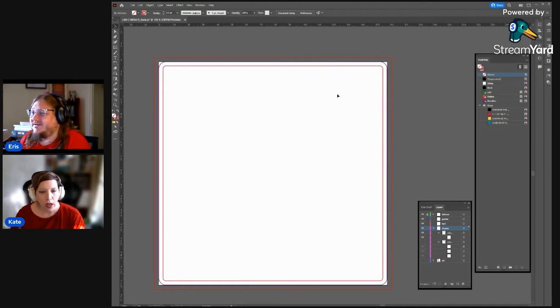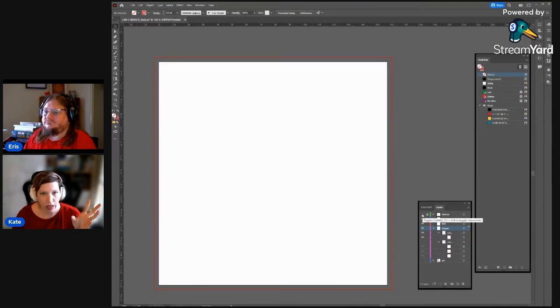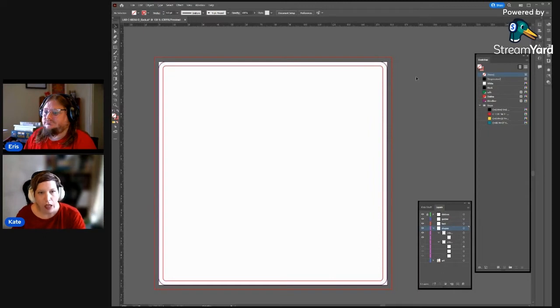All right, so when we open up our AI template, this is what we're looking at. We've got literally just a die line. I'll turn it on and off so you can see it nice and clearly. So what we're aiming to do today is to create a new shape. We're going to create our custom shape. We're going to pretend that we're making a game that happens to have a pentagon shape in it, because we don't offer a pentagon with LaunchLab. So it is something that a person would have to create. So we're going to make a pentagon shape.